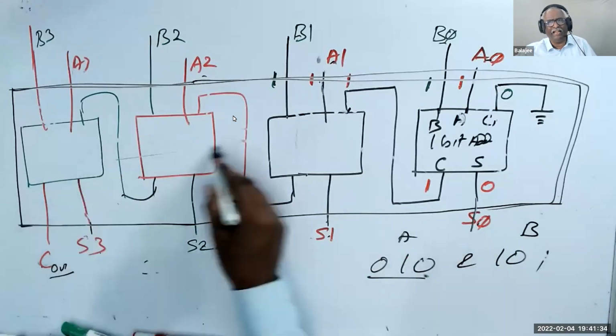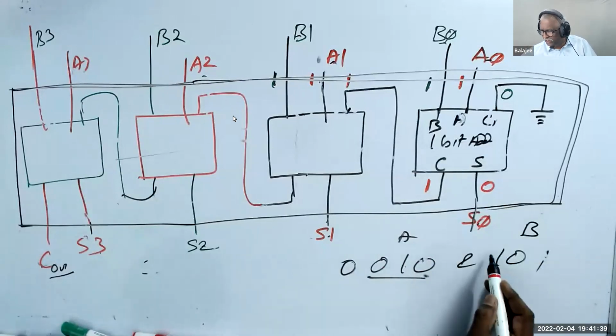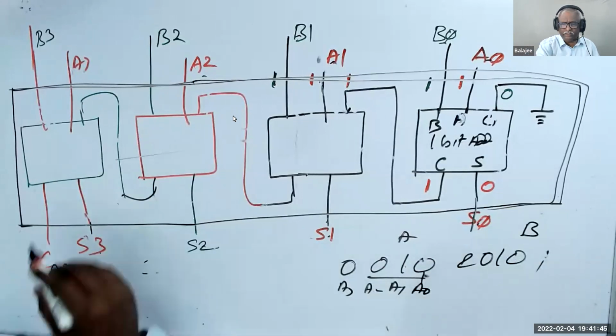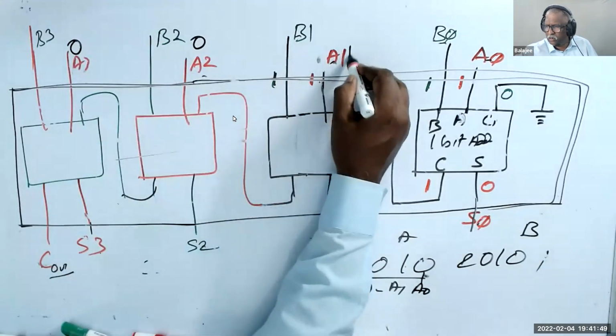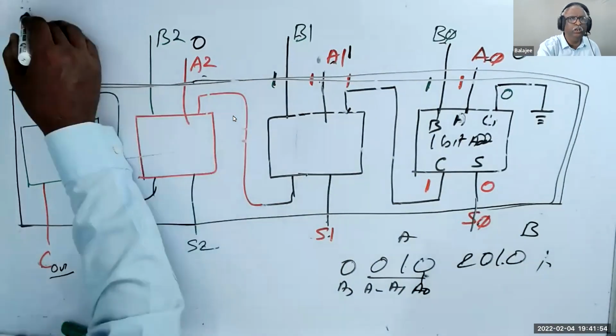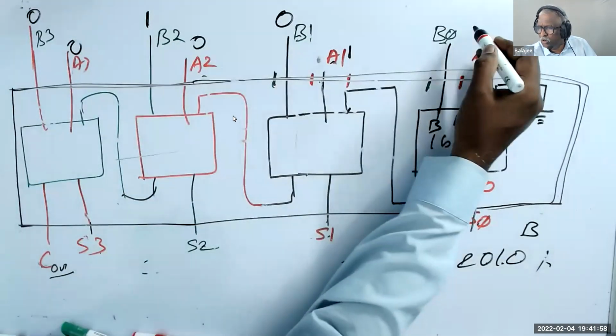And we have a 4-bit adder. What do you have, a 3-bit? So you have to add a 0 here, as a prefix. And you add a 0 prefix. This is A0, A1, A2, A3. That is 0, 0, 1, 0. What is B? 0, 1, 0, 1.